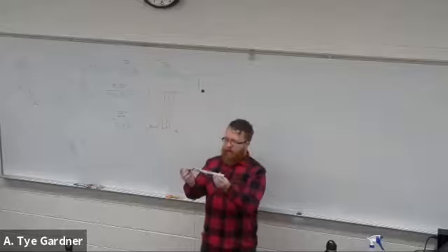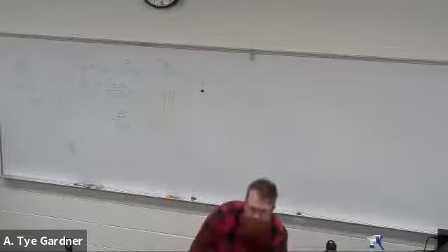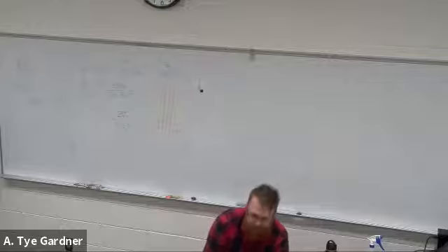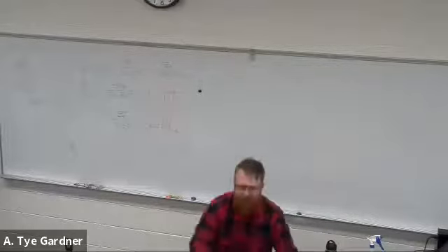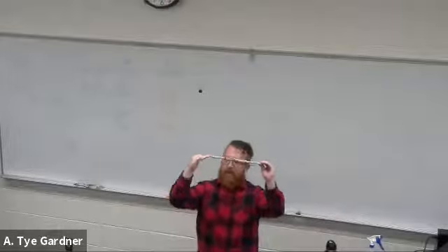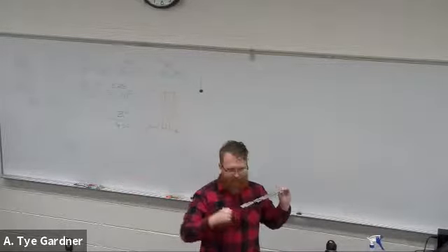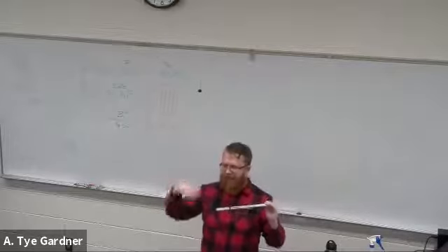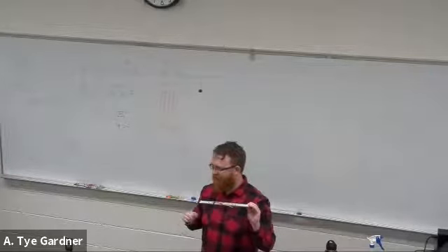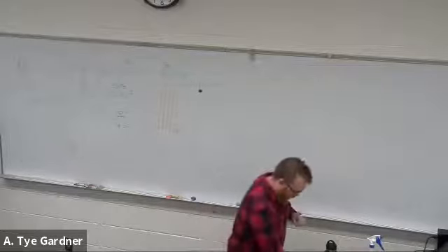So the way you would measure something, like let's say we wanted to measure weight with this beam, we would go get a C-clamp and clamp it to the table. We would then use a weight or a couple of weights to calibrate it, and we hang it on the end here, right? We clamp this side, put weight on this side, and it would bend. Once we have a couple of points using a known weight, we can use our linear estimation to create a curve, and then we can put on an unknown weight and use the strain to measure what the weight is. So this is a real way to use this sensor.